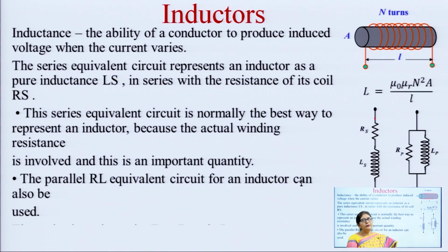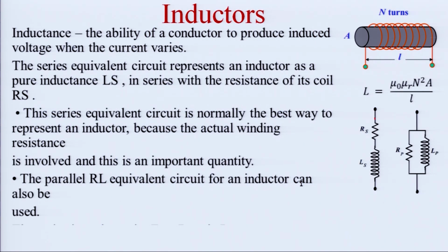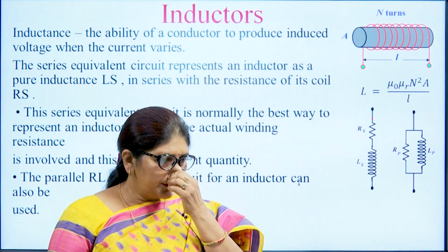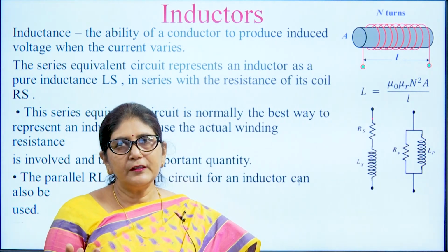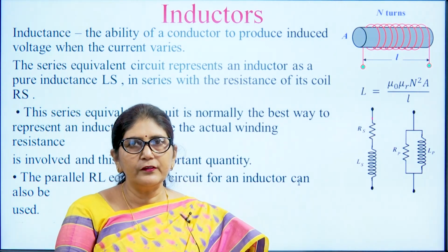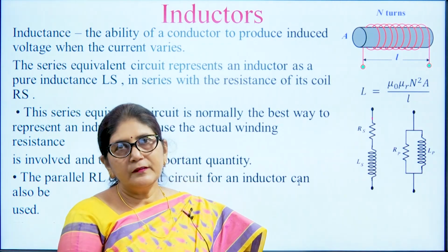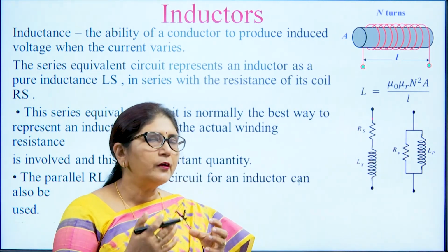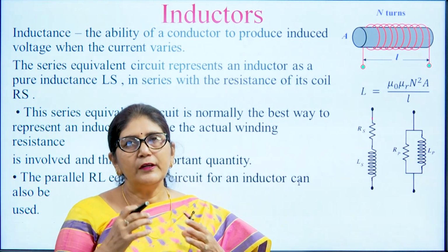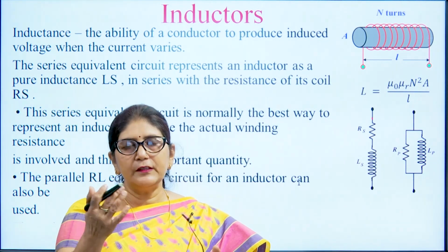Similarly, inductances are also used, and in AC bridges we can measure the value of inductances. In inductances again we can represent it in series combination or the shunt combination. When there is a pure inductance, we represent it with series resistance because the coil has some resistance value.